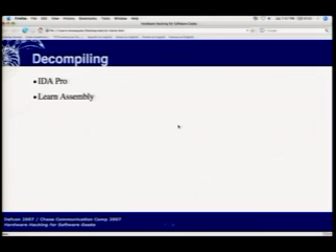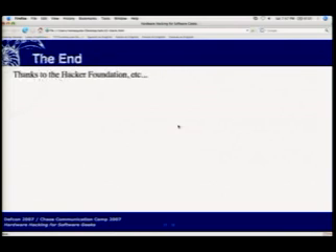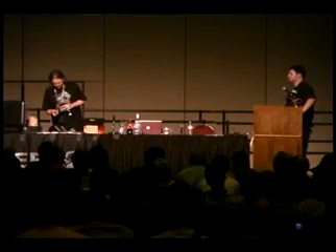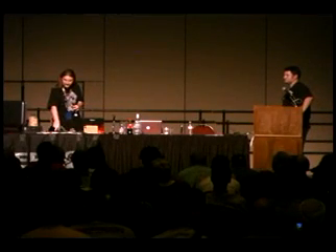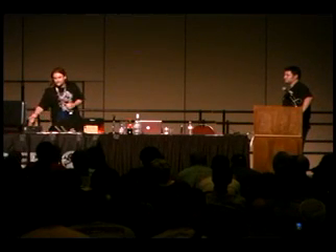It's 2 minutes. Okay. I actually have one up here. It's incredibly ghetto looking and got me all sorts of funny looks on the airplane over here, but that's the card reader, and I just desoldered the socket and then hooked up little metal bits to connect. They basically clip onto the chip itself. And then you can just use DD, you get a hex image out of that, and throw it into IDA Pro.